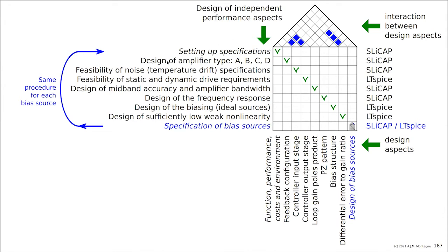Now, of course, a bias source is not a 4-terminal element. But in many cases, we make, for example, a current source by starting with a voltage reference and making a transadmittance amplifier. You could even model a current mirror as such if you only use it for biasing.